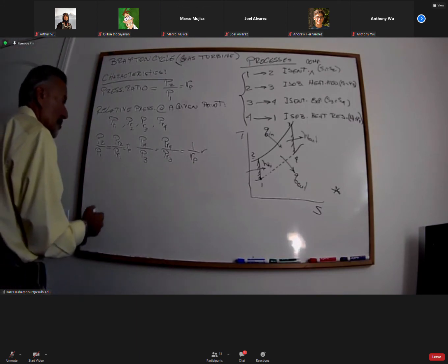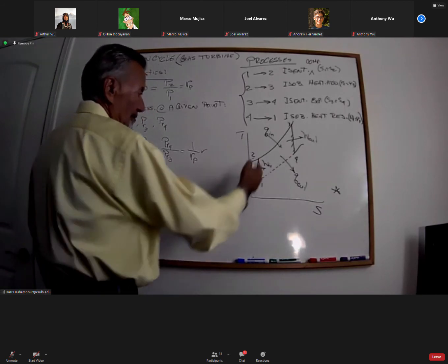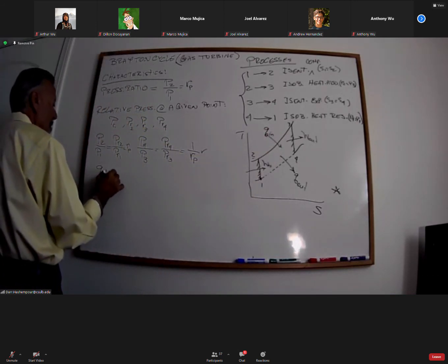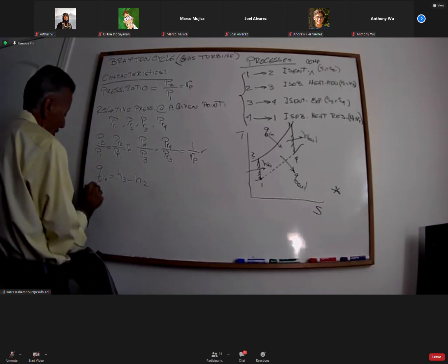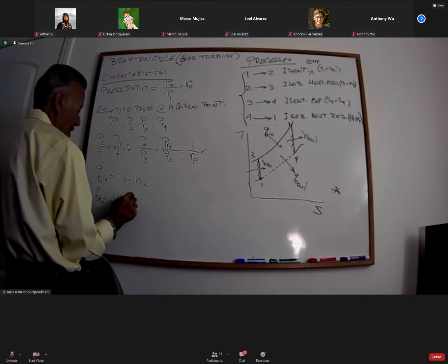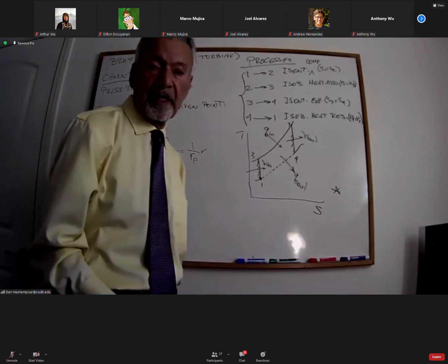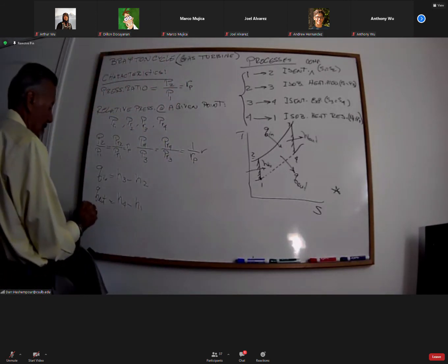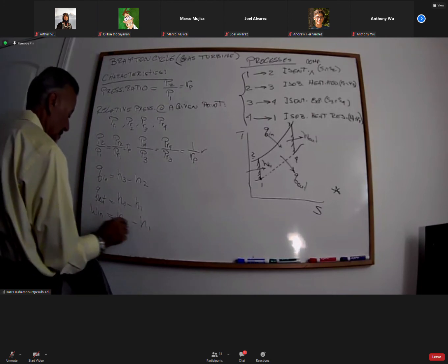Now, going around the cycle, finding the quantities of various energy, our Q in is equal to H3 minus H2. Our Q out is equal to H4 minus H1. There is no constant volume here, so everything is delta H across the equipment. Work in is H2 minus H1.